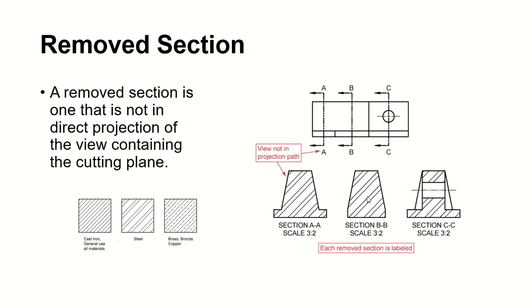Then of course another section, BB. We read it A and then A, so section AA is this cut, section BB is that cut, and then section CC is the one cut through the circle. So here we have a cylinder, and you are looking that way, okay? Be very careful with this: there's no circle right here in this spot, so there's nothing here.